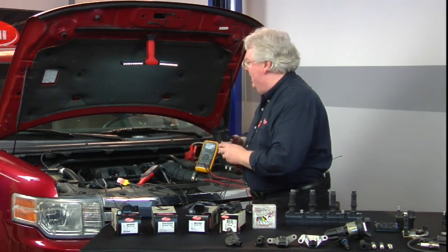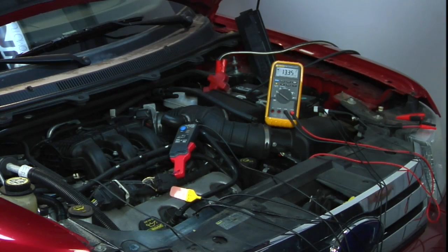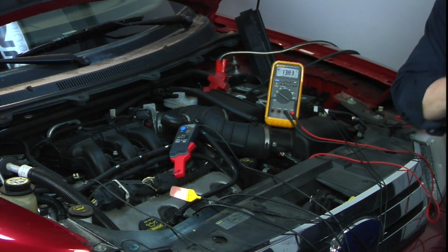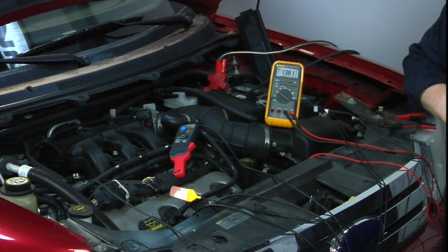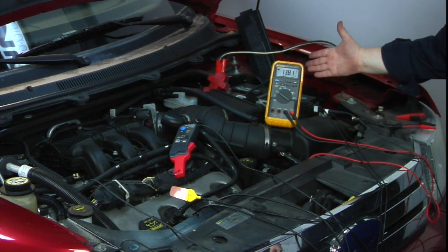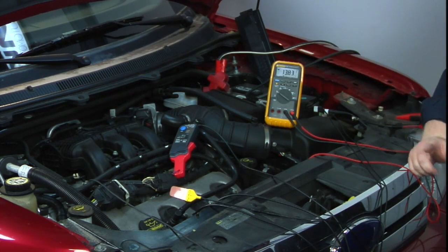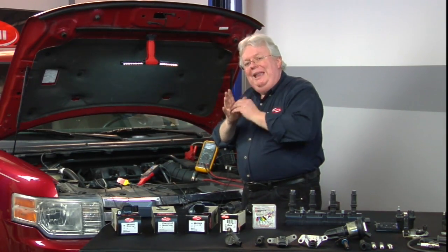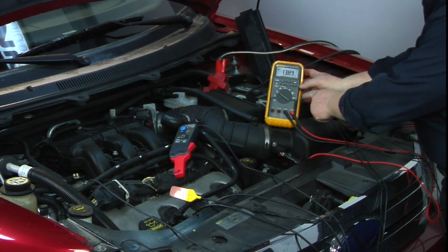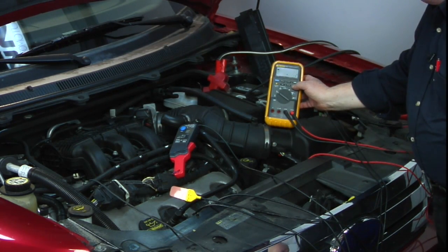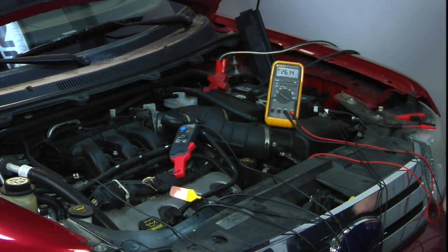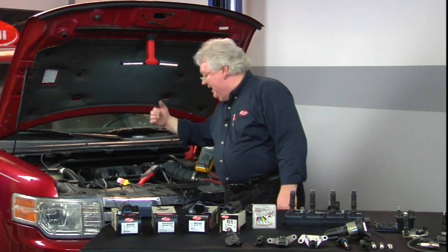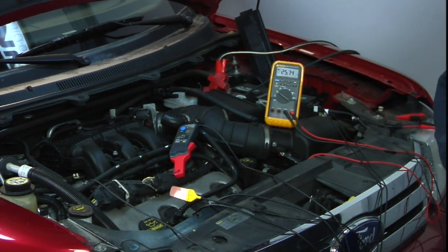Now when we start the engine, go ahead and start it up, Allison. The voltage is slightly lower on the meter because we're seeing an average of on versus off time. It's mostly off and a little bit on. That's why the voltage is down just a tad. Now if we change it to something more realistic with the meter, because the meter's now seeing the negative supplied ground from the PCM, we should see a pulsing circuit. We'll turn it to frequency, and sure enough, we see a steady 25, 26 hertz. That's 25 to 30 times per second that cylinder is hitting, that coil is working.